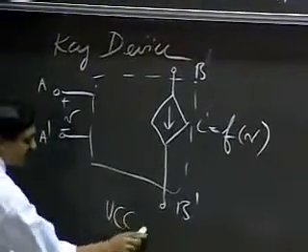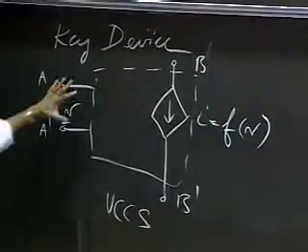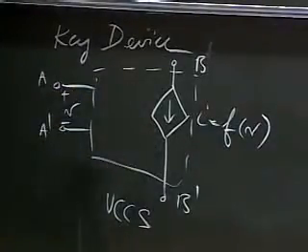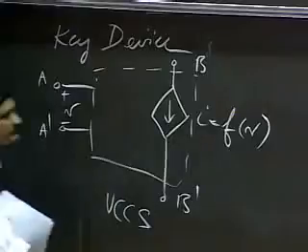So this is a voltage-controlled current source. What I'm going to do is talk about a device that can give me this behavior or some close approximation to it. It turns out that under certain conditions, the MOSFET that you have already looked at behaves in this manner. And let me show you under what conditions the MOSFET behaves in that manner.